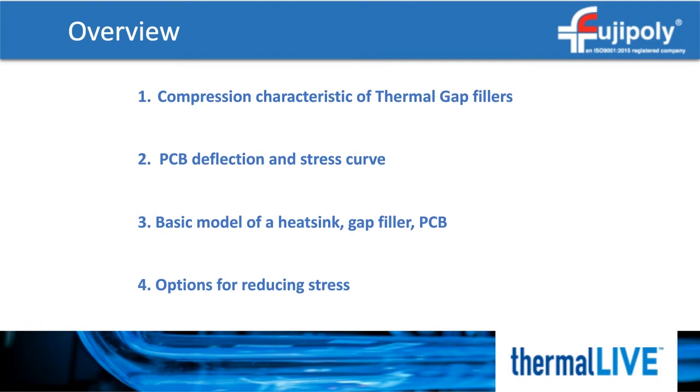Before we start, I would like to do a quick overview of the topics we will be discussing. First, we'll look at the compression characteristics of various types of gap fillers, from standard viscoelastic materials, putties, as well as form-in-place. We'll look at some stress-strain curves and relaxation over time.